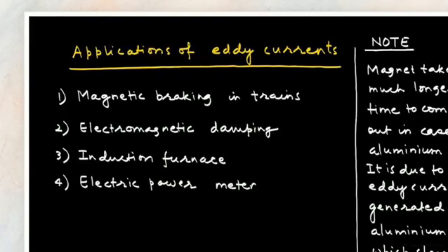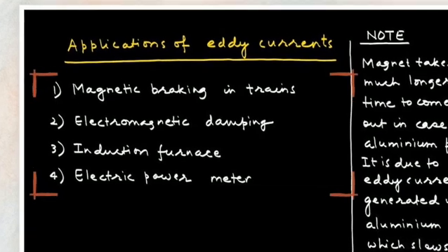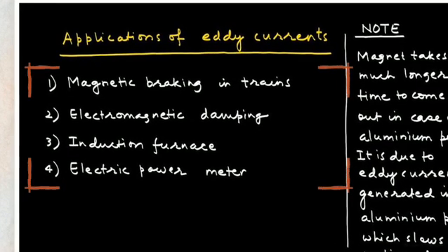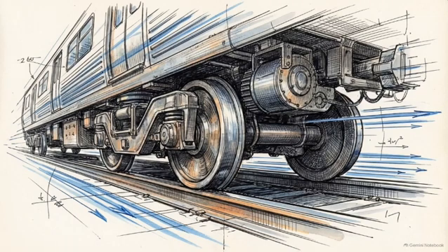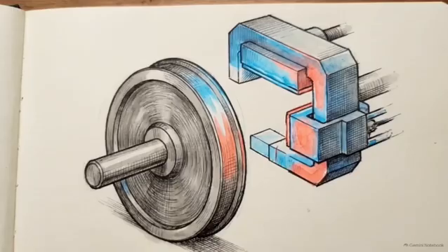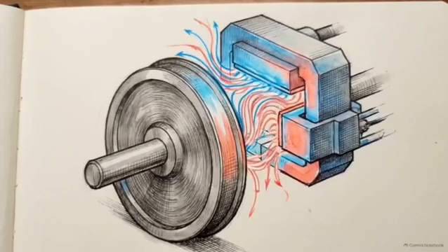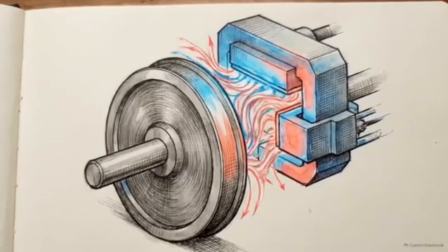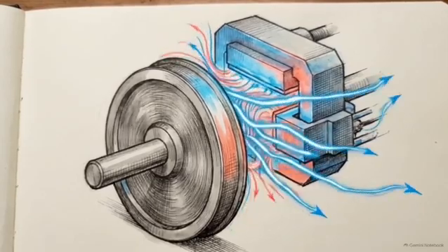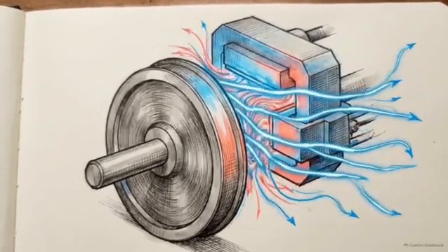Moving past laboratory experiments, engineers scale up this physical phenomenon to harness extreme drag and generate massive thermal energy in heavy industry. The exact macroscopic damping force that slows the falling magnet is identical to the mechanism used to slow mass transit. Placing powerful electromagnets near the solid, spinning metal wheels of a train induces massive eddy currents on demand, providing extreme deceleration through non-contact induction.